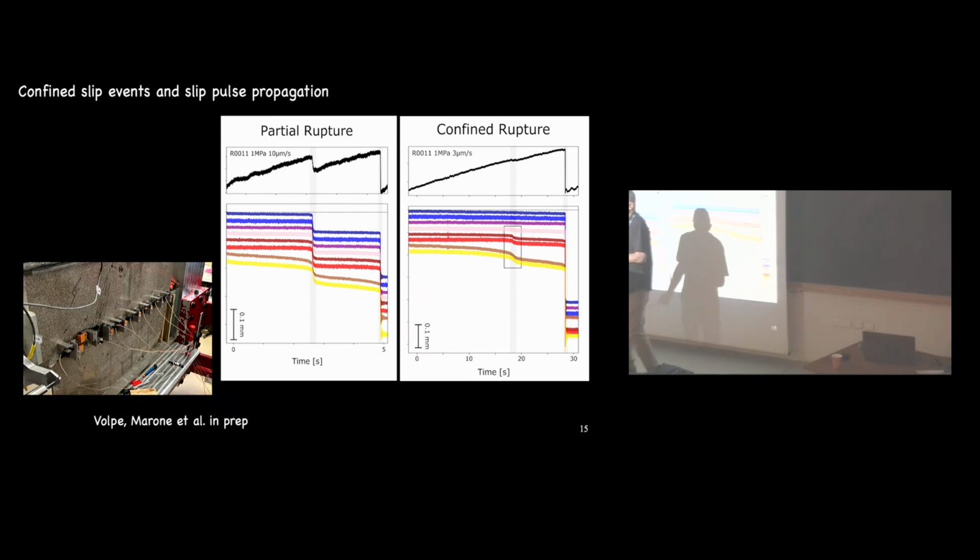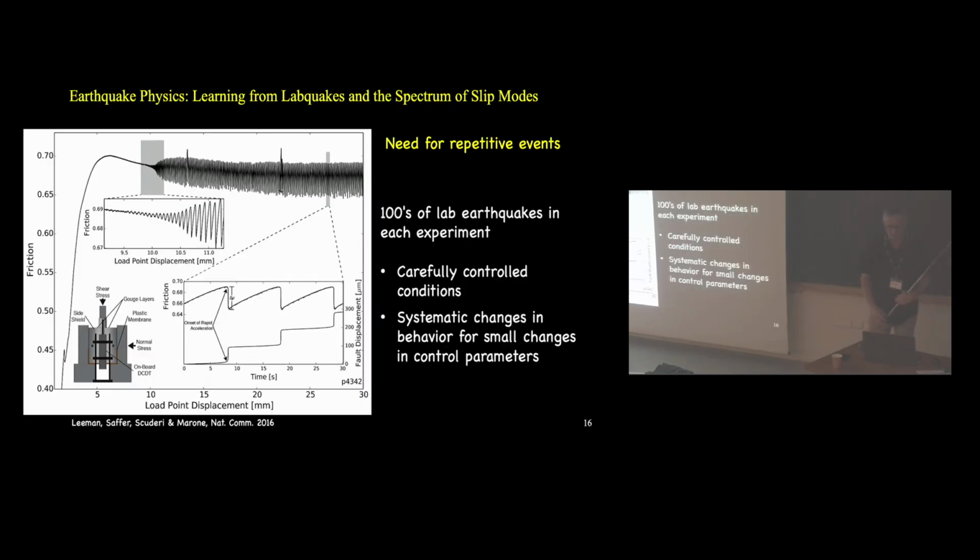And this is a single direct shear configuration where, like everyone else, we produce another slip surface up here on the top that allows this block to move relative to this one, either with Teflon or Molykote or some kind of lubricant. And you can see that this end of the fault is slipping, this one is not. And there's a little hiccup in the stress-strain curve, but nothing super major about it.